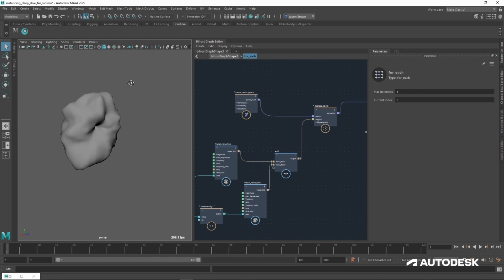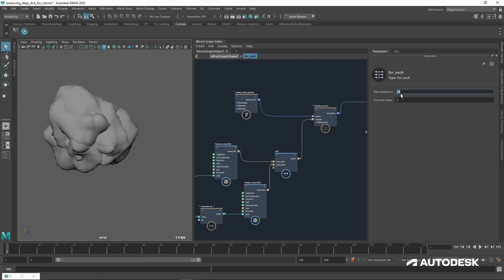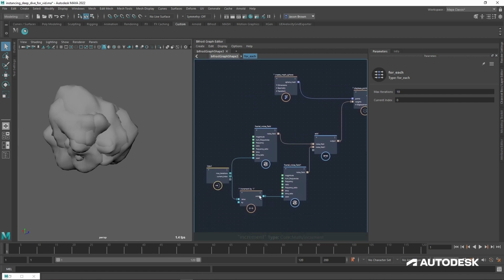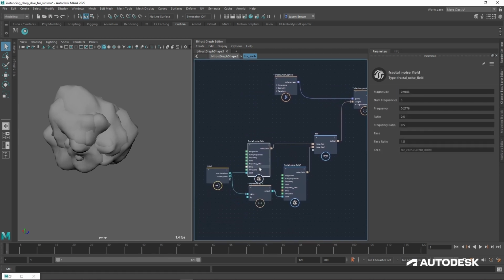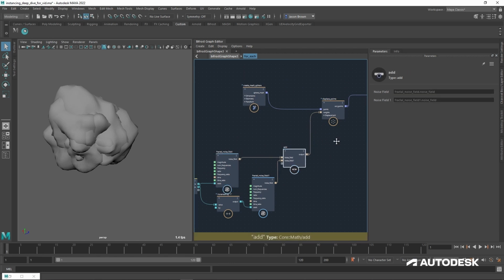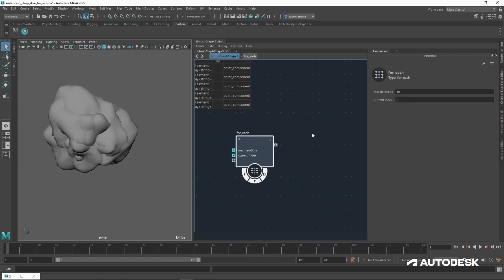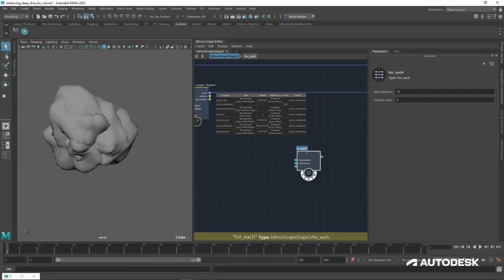They're pretty weird and wonderful, but they are also quick. So let's change our current index back to 0. We've had enough previewing. We'll change our iterations back to 10. As I said, not the world's prettiest rocks. I wouldn't want to render them close up, but plenty good for our purposes. So we get up out of there. So we've now got what essentially is a rock generator.